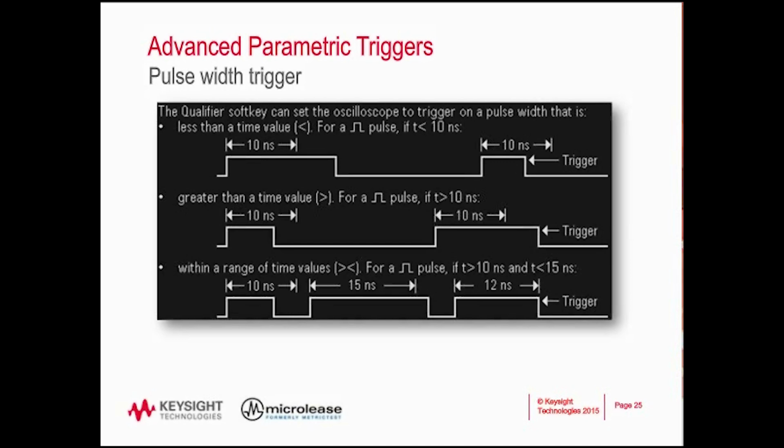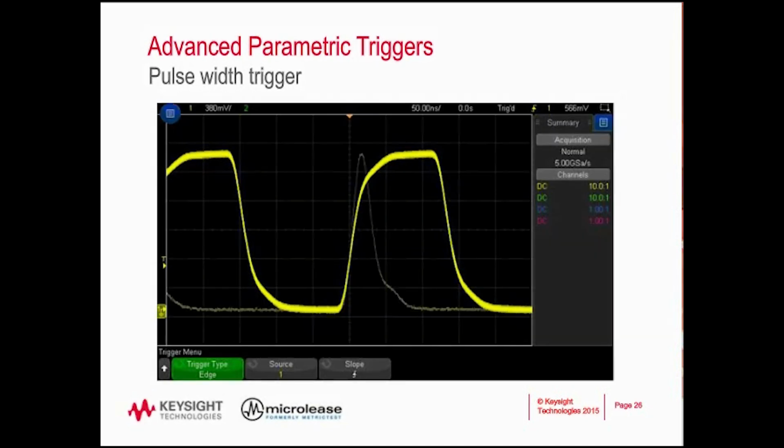Again, let's take a quick look at an example of why you would need a pulse width trigger, how to set it up, and then alternatively how to use zone trigger to accomplish the same task. First, let's take a look at this glitch signal that we've encountered in the past. It doesn't look like the slide's animating, but we'll see it here shortly. What we're looking at is actually a clock signal with a 1 in a million glitch popping in and out of existence in the middle of the screen.